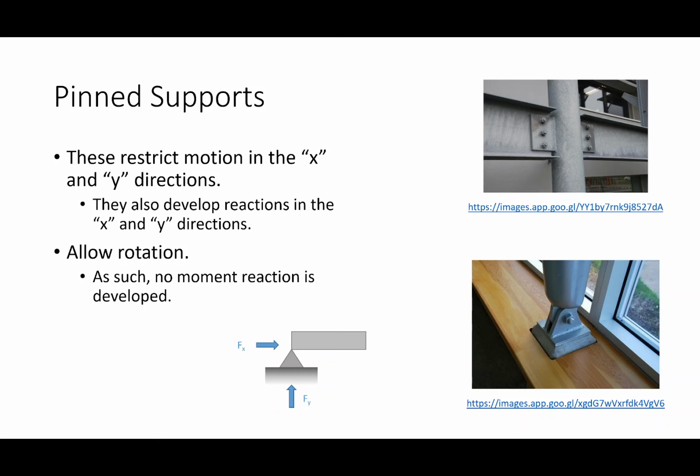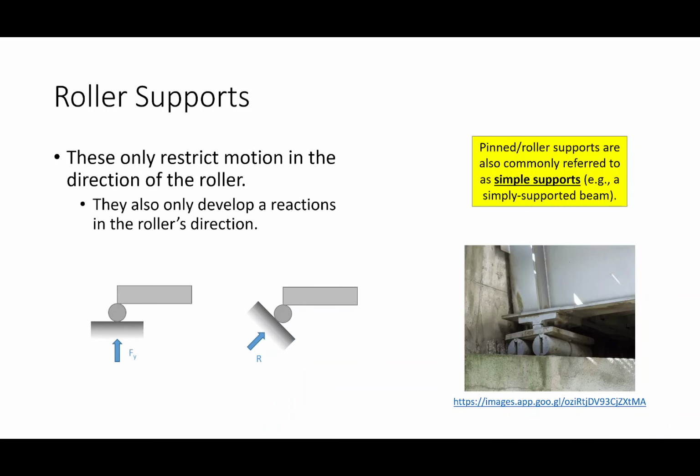The other common one is a roller, okay? So a roller is intended to only withstand forces in one direction. So it will allow rotation and allow translation in one direction.